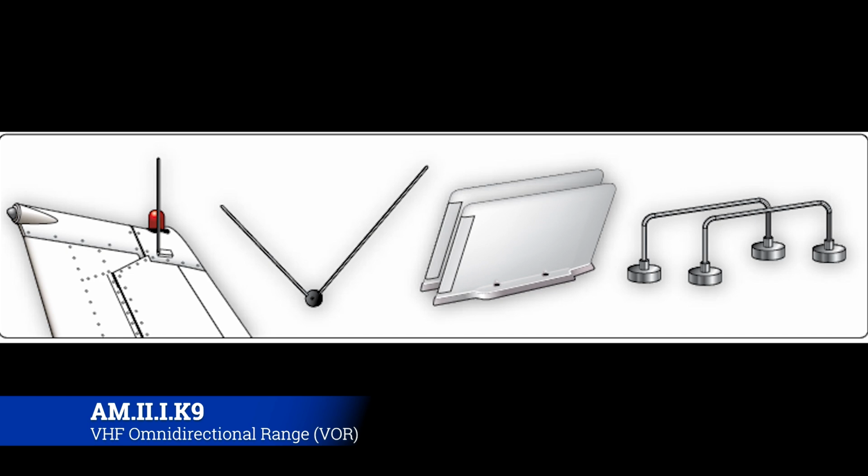Okay, so on the airplane, what do VOR antennas look like? They can look like any one of these. The most common one is going to be the second from the right, the little V wires, and typically they're affixed to the vertical stabilizer, with the V's kicking out aft, kind of like an arrow point going into the wind. But there can be other ones, so blade antennas are also used. That's what's on the Lear.